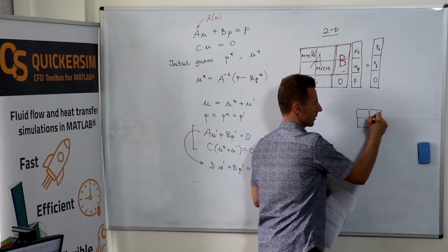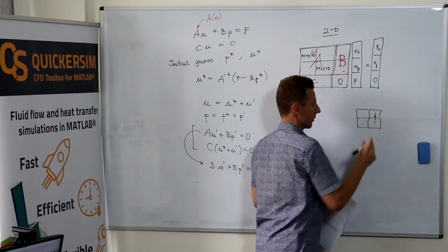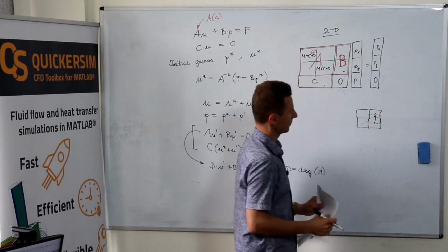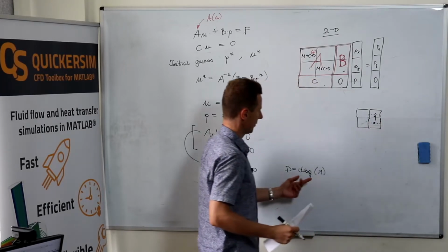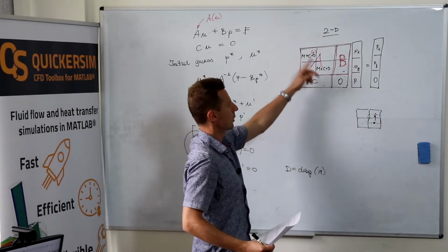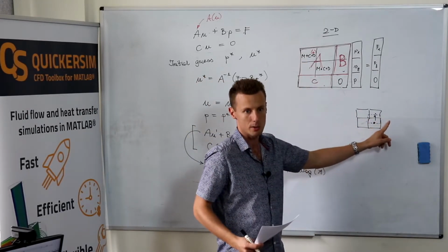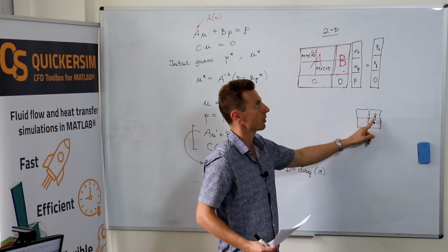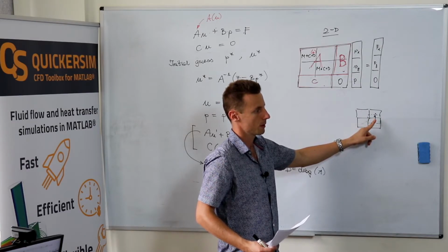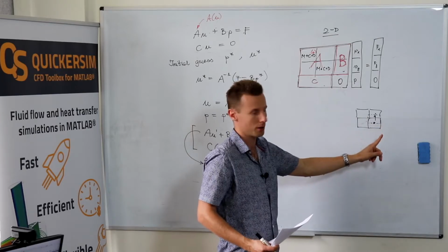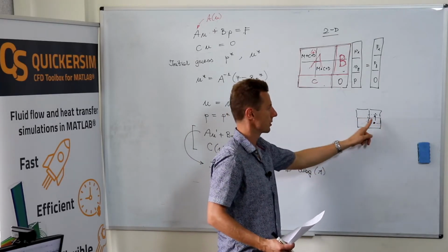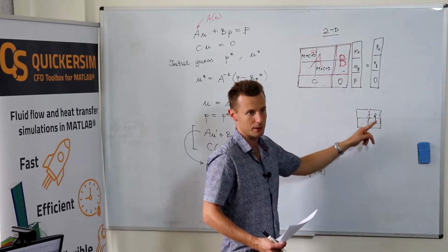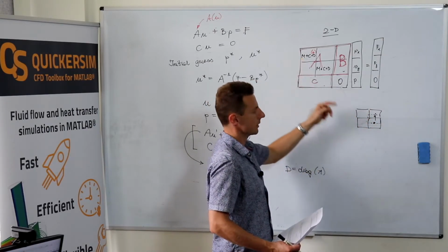In the finite volume method, if you're discretizing the equation for the y component and you're drawing such a finite volume, then dropping the other terms means dropping everything associated with the viscous terms and only representing the part of the convective term, part of the diffusion term, because it also contributes to my coefficients but does not relate directly to the velocities at the neighboring components, and it still includes the inertia.